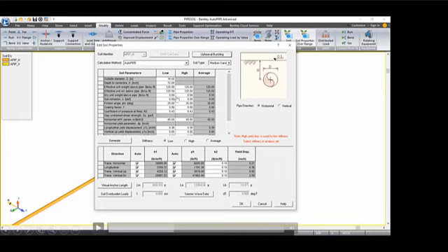The software recognizes by default some parameters, and you can declare, no, I disagree with this friction angle. I will put a different or other coefficient or similar, okay? After that, the software determines stiffness and springs depending on the stiffness that you consider, low, high, or average, okay?